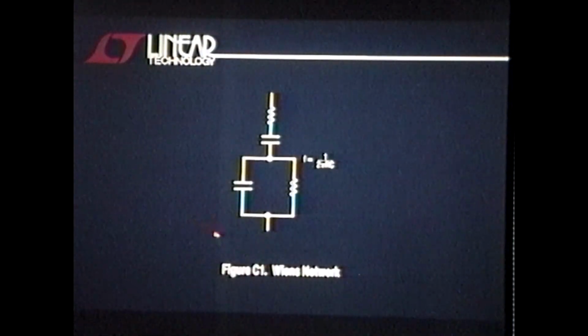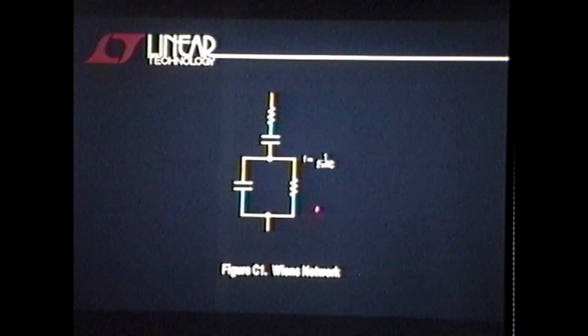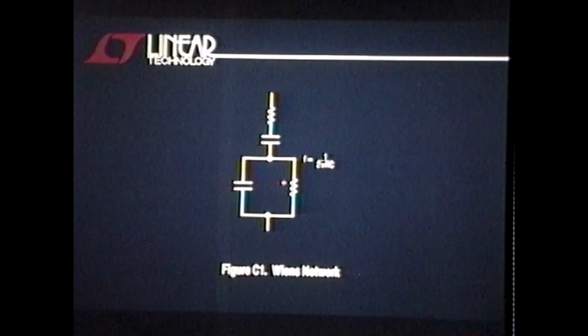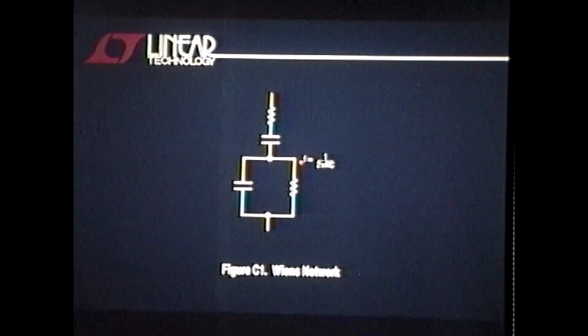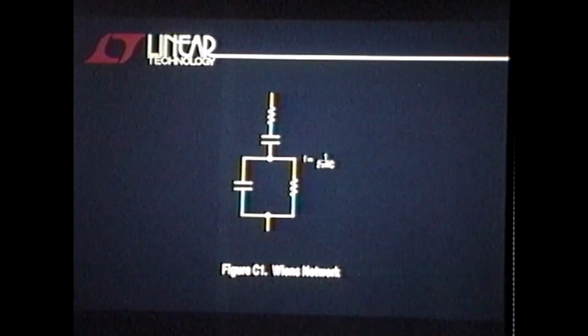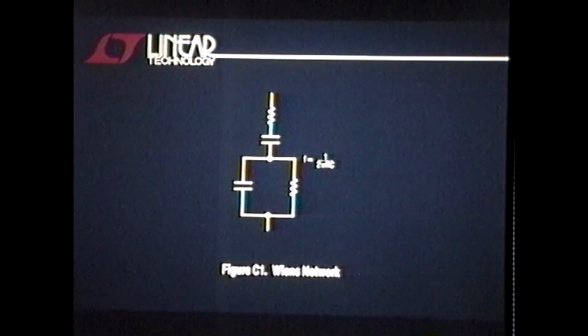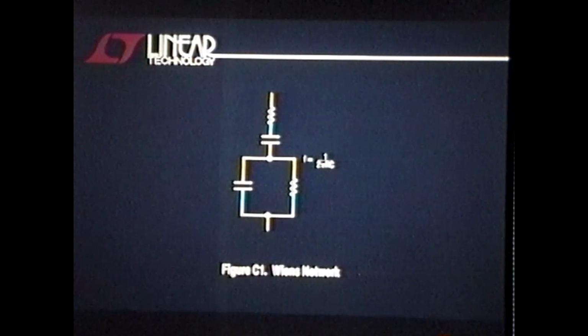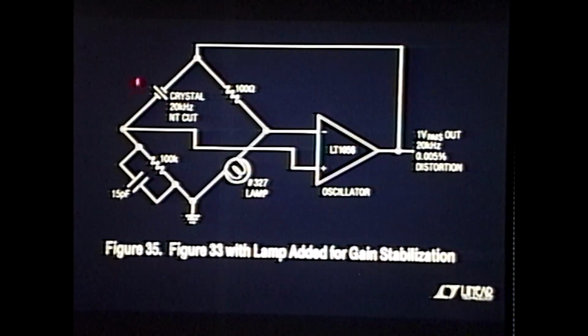Yeah, there was a Professor Max Wien, and in 1891 he came up with this RC, parallel RC configuration. Resonant frequency F is 1 over 2 pi RC. Well, in 1891, Wien probably wasn't trying to get it to oscillate, because in 1891 he had no source of electronic gain available. What Wien was doing is he was balancing bridges for use in telephone circuits. He was building bridges. And that's what he used the network for, and it promptly became buried till Hewlett picked it up, threw out Meacham's crystal and dropped a Wien bridge in there.